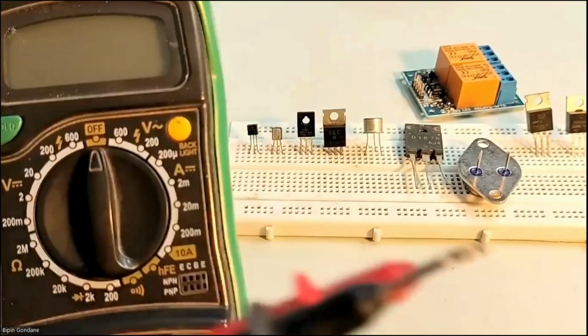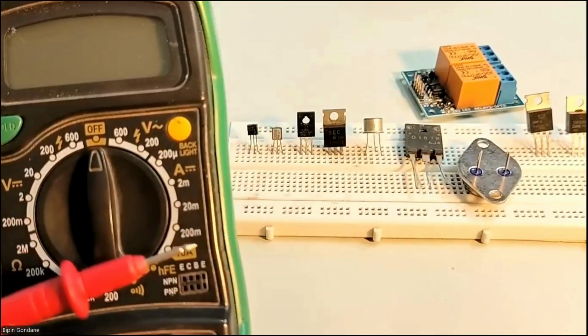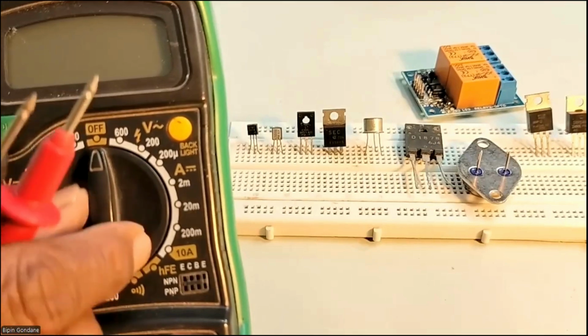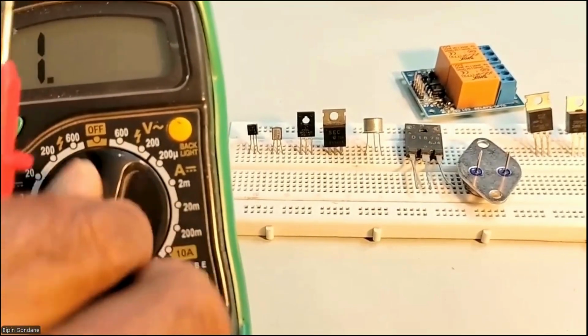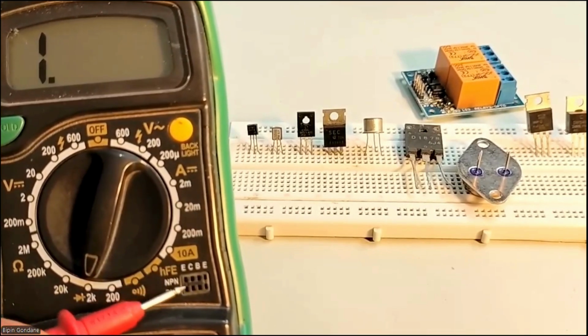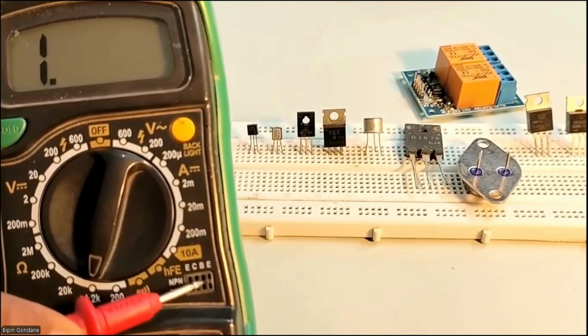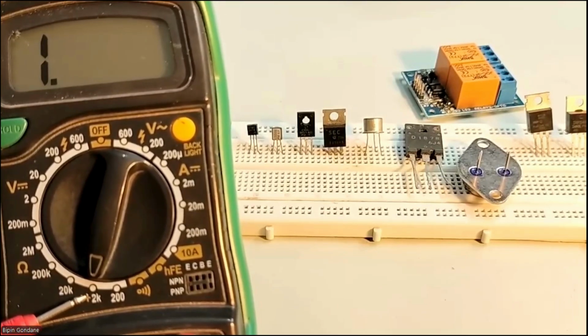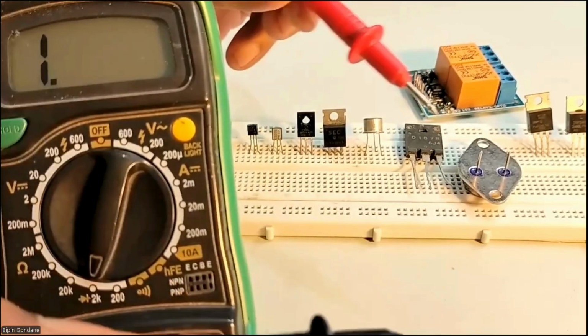You can see there are two probes coming out from my meter, red and black. My meter is off. While testing the transistor, like I told you with diodes, keep it in diode mode only. Please remember there is another way, the transistor hFE with PNP and NPN holes given, but my suggestion would be to test it in diode mode, because our transistor also has diodes inside. In a diode you have only P and N material, that is only one junction, but here we will have two junctions.